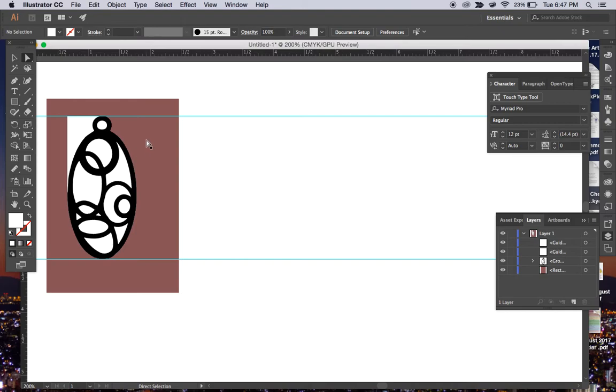And the only reason we can tell that is because I put the pink back there, so that lets you see what's going on. So again, click on the white, click delete. Do that also for anything that's in interior space that you actually want to have cut out, because you don't need to cut it twice. If you cut it twice, you might melt your acrylic or burn your wood. Two laser paths are going to be way more than you need.